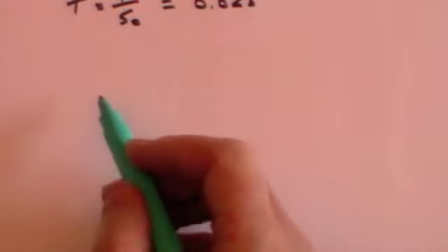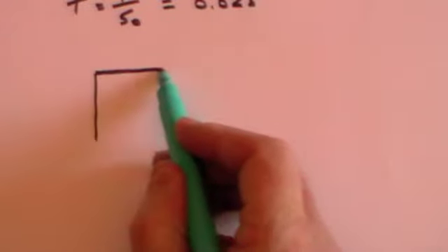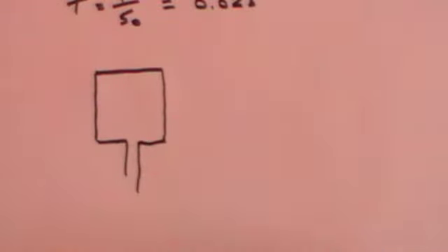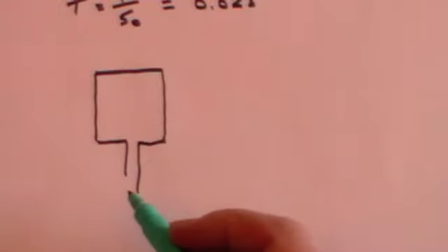In the UK, there are 230 volt sockets in the wall, and they are the source of the supply, and in order to attach an appliance to them, we plug them in using a standard 3-pin plug. And if you open a 3-pin plug, which you should never do if it is connected to the mains, so always make sure it's disconnected, you'll find that there is a thick cable coming in, but within that thick cable, which always has a plastic surround, there will be 3 other cables, also with plastic surrounds.